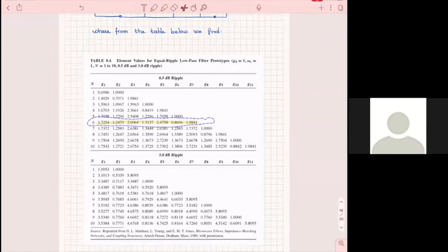That is interesting, which means, what does that mean in design? If you have another component in your receiver after the filter, this component needs to present to the filter not 50 ohms, but whatever impedance the filter needs to see. For the filter to perform well, because if you don't provide that impedance, the filter is not going to perform at its best. Okay, so we now have these numbers for all of the G elements.